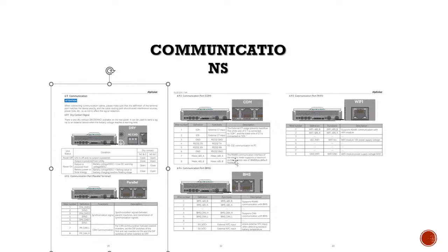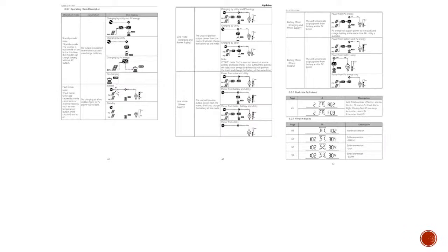So when you see this, it means that your PV is supplying, then your grid also is supplying, right? So when you see this, it means your PV directly is supplying to the battery, right? But when you see this one, it means your PV is supplying to your load. This one, power from PV energy only. These are just interface showing you. So I think this one, power from solar, battery, and grid supplying to your load, all three of them. So this inverter is compatible with both grid and solar to supply your load. Yeah, continue.